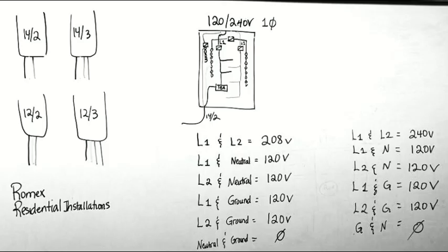So for example, if I'm taking a measurement right here, the total amperage of the circuit is going to be the same here, at this part, at this part, and at this part. Our constant value in a series circuit is going to be the amperage, right? That's a way that we can recognize a circuit that is in series. What would be another very important way to recognize a series circuit? Add up.